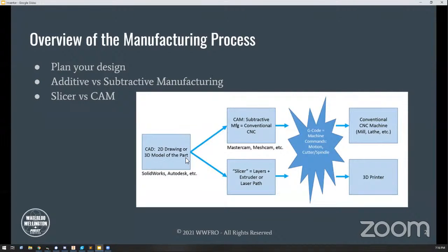As you move through this process, you can run through CAM, which is basically telling a machine which tool to use to cut which aspects of the part, and it generates something called G code, which you basically never really see. And then finally it's sent to the mill for processing, or the lathe.